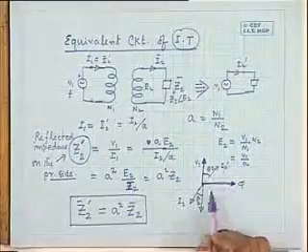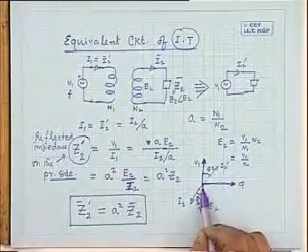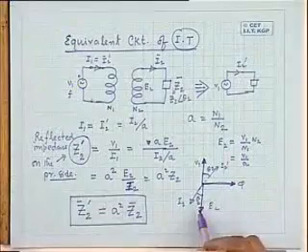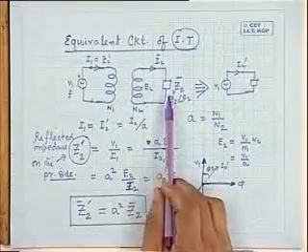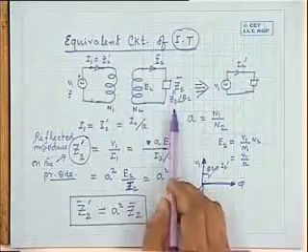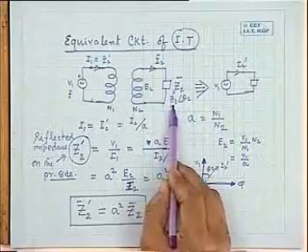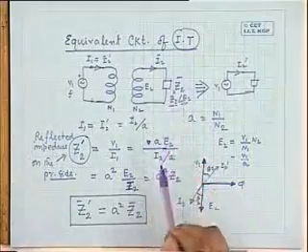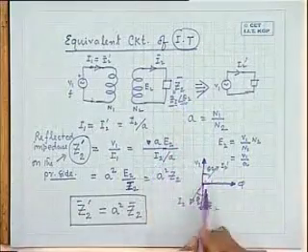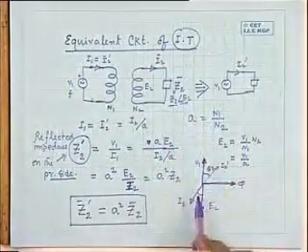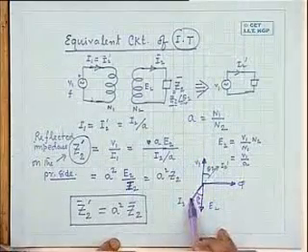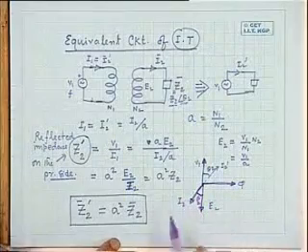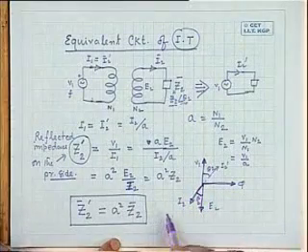This is the supply voltage V1. Flux will be 90 degree lagging. Induced voltage will be E2 here. Suppose on the secondary, instead of connecting a purely resistive or purely inductive load, I have connected an impedance whose magnitude is Z2 and angle is theta 2. So where will be that phasor? Suppose lagging power factor, theta 2. So it will be positioned here. I have drawn I2 first.